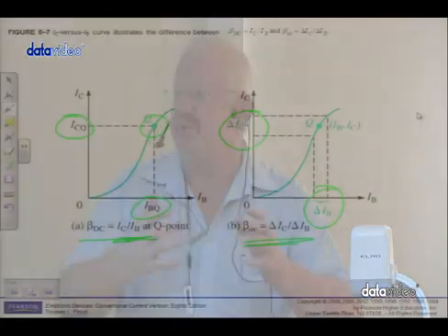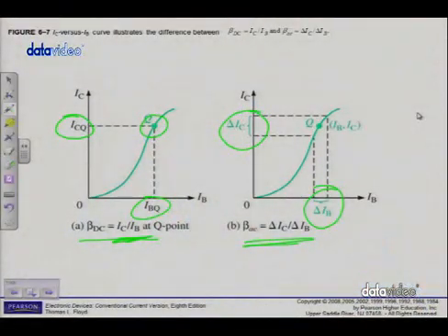Alright, on page 262, I'm just going to do the introduction of the H parameters. You can underline that first sentence. It says a manufacturer's data sheet typically specifies H, or hybrid parameters, like HI, HR, HF, and HO, because they are relatively easy to measure. So the manufacturer uses these values to do some measurements to give us more information on the data sheet of a specific device, which we can then use when we design a specific circuit, be it an amplifier or whatever.